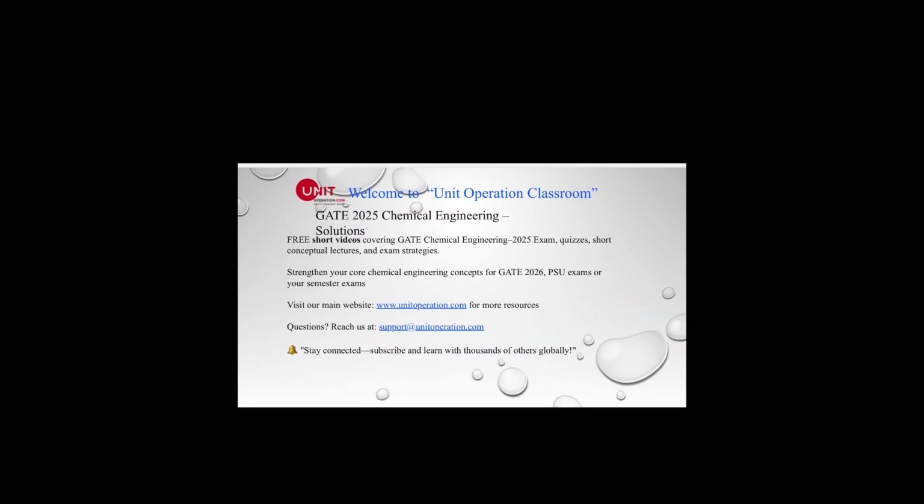We know the values of PB and PA, we know the value of rho, we know the value of eta, we know the value of Cp. So automatically the value of TB minus TA, that means the rise in temperature, can be calculated, and that comes to be equal to 0.142 degrees Celsius. So this is our answer. Detailed calculations, of course, are shown next to this particular.